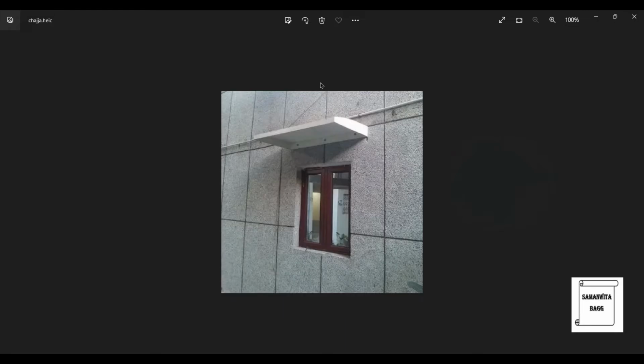There is another type of sunshade that I found for you. It looks like this. Generally you must have seen that the fixed end, which is connected to the building, is a little broader compared to the other end. The reason is that it is subjected to its own weight. So the maximum stress would be generated at the end connected to the building, and that is where you need to add more material. On the other side, you can reduce the material.